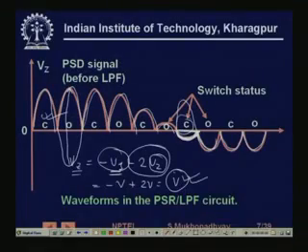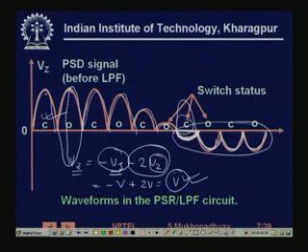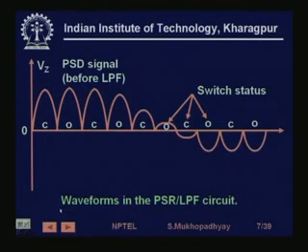So you see that when there is a phase inversion, the signal goes negative, it's rectified, but it's rectified in a phase sensitive manner. It's not an ordinary rectifier. Now, if we send it to a low pass filter, then you will get the envelope of the wave. If you get the envelope of the wave, then you are getting back the motion. So this is the basic principle of phase sensitive demodulation, and it is applied in various types of inductive and capacitive sensors.